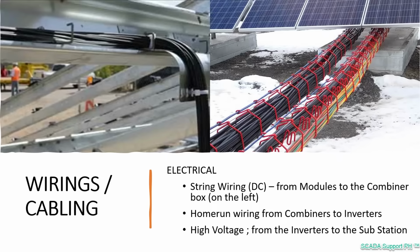Then we bring all your strings together to a combiner box. Then we move the combined wires coming from multiple combiner boxes into a home run wiring towards the dedicated inverter. That's the image on the right.